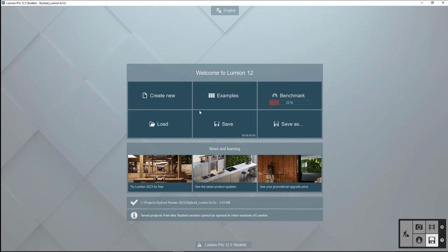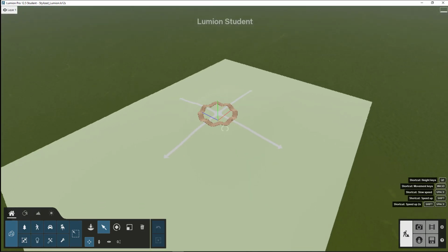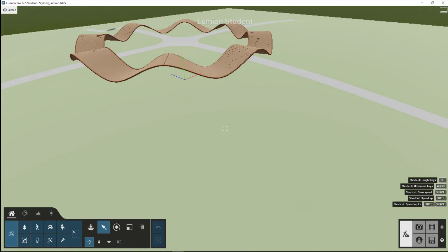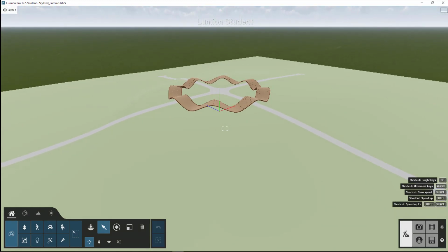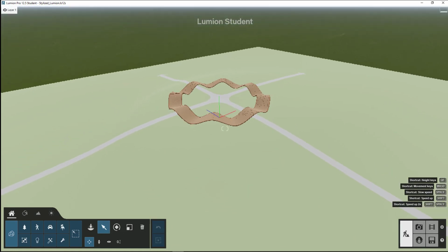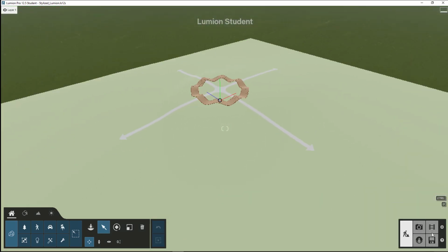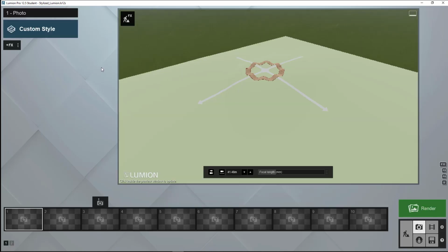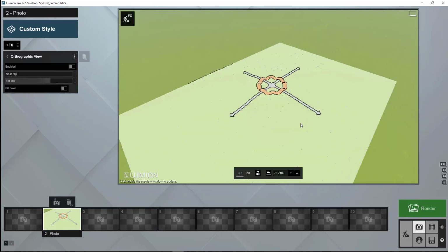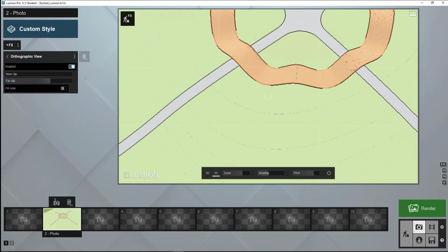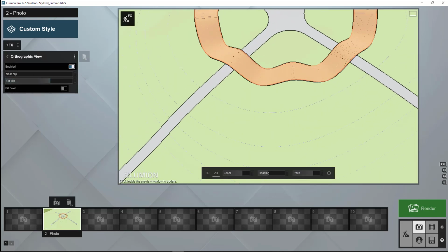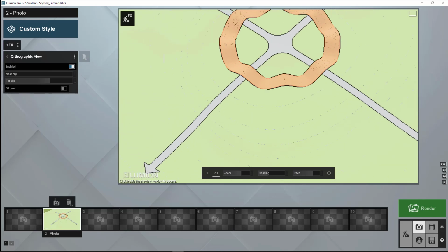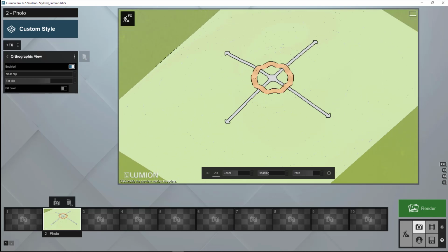You'll see. So I have saved the file. I'm going into Lumion, and there's the first version of my arrows. They're pointing directions. Now the initial target of Lumion is not to create a realistic render. So I'm directly going into my render settings and creating an orthographic view through the FX. This would help us to get a clearer diagram.